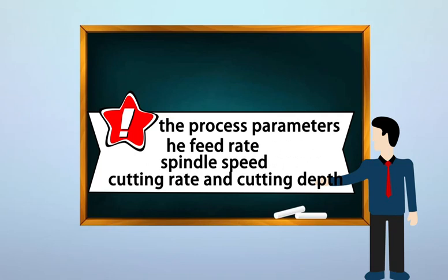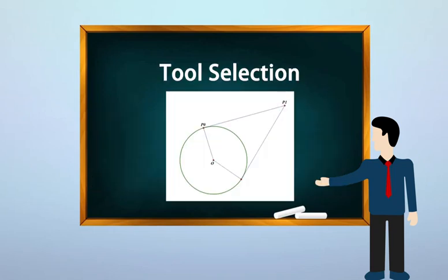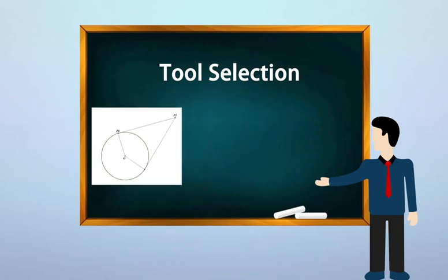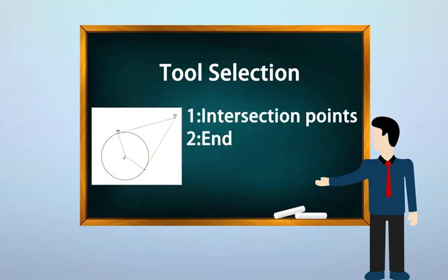Next, numerical calculations should be carried out. Most systems have a tool radius compensation function. You need to calculate the coordinate values of intersection points or tangent points of adjacent geometric elements of the shape, and obtain the coordinate values of the starting point and end point of the geometric element and the center point of it.